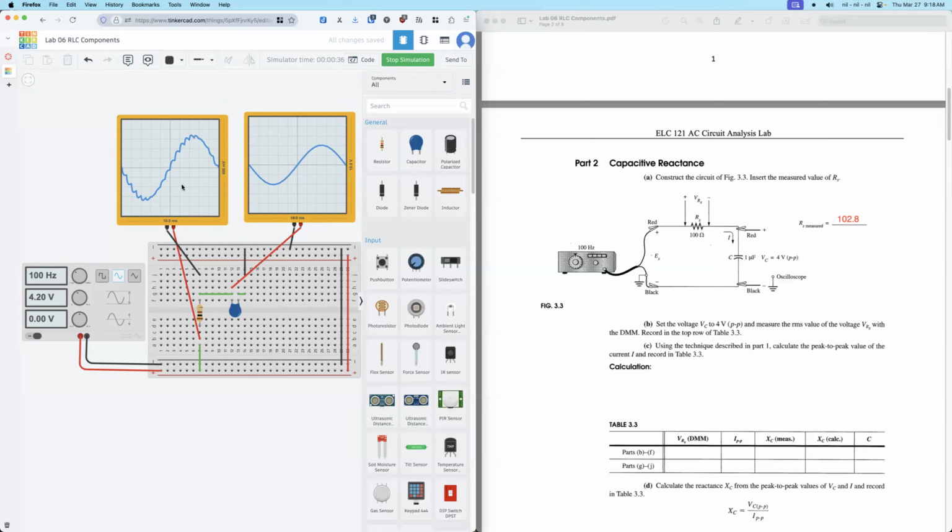Then for this one, the setting here is 400 millivolt. So we know from top to bottom, each division is 40 millivolt. Then we can count. This may be 0.2, so 1.2, 2.2, 3.2, then 4.2, 5.2, 6.2, another 0.2, maybe 6.4.